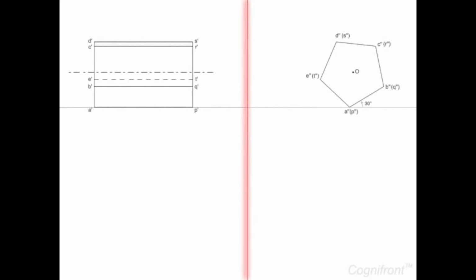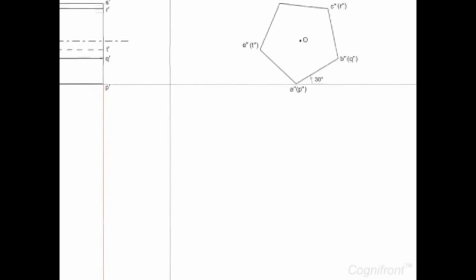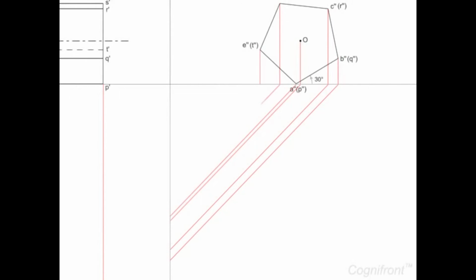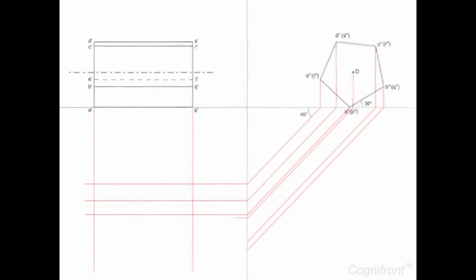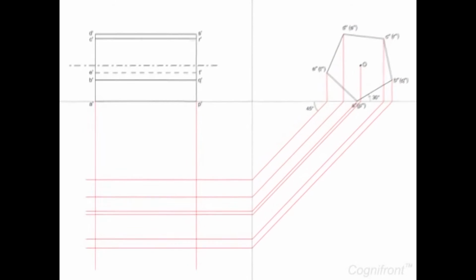Consider a vertical center line MN between the front and the side view. Extend vertical projectors from A' and P' below line XY. Project the corner points from side view onto XY. From these intersecting points on XY, draw lines at 45 degrees to meet line MN. These lines are further extended horizontally parallel to XY, meeting the projectors drawn from front view.